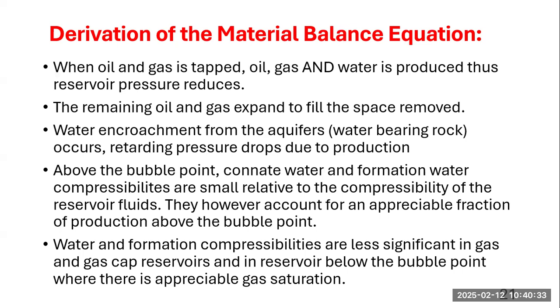So below your bubble point, as soon as you have the evolving of your gas from your reservoir, or you have the presence of your gas cap, your formation compressibility, your CF, and your water compressibility, your CW, are all less significant because you have the presence of gas in your reservoir, either as gas cap or as solution gas. Because the gas is highly compressible, CW and CF are far less than CG.